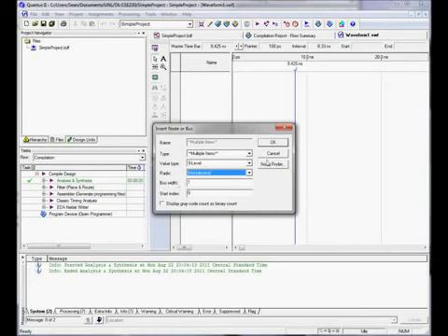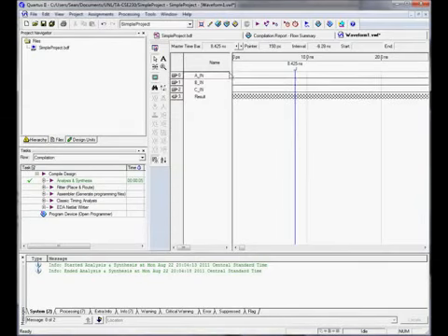Our bus width is 1, just means we're 1 bit wide. We'll say OK. So right here we have these are all of our inputs, and then our result is an output, and it lists all these little hashes right here because we don't have anything going to it. So we need to put some inputs on our different lines here.